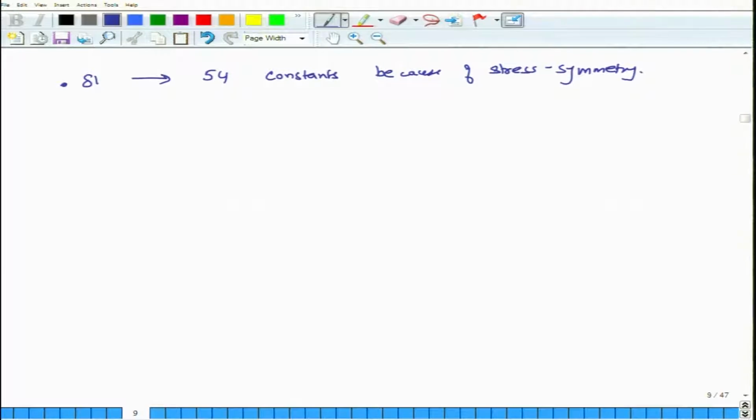Next, look at the strain tensor, epsilon KL. For shear strains, epsilon 12 is defined, if all these are linear strains, and these definitions you have already seen in your earlier textbooks, as half of del u1 over del y plus del u2 over del x.